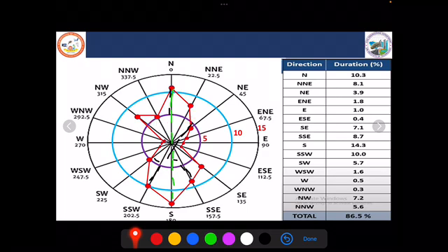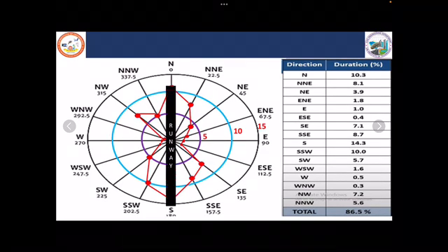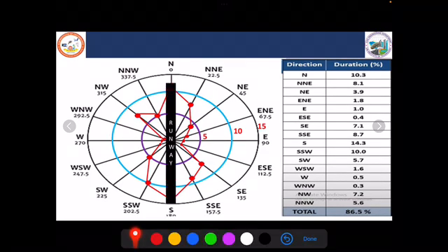So this is the direction which is best suited for the runway, where we can have the maximum wind coverage. Hence the runway will be located along the north-south direction. Next, the runway is located along the north-south direction, but we have to check whether the prescribed wind coverage can be achieved with this direction or not.